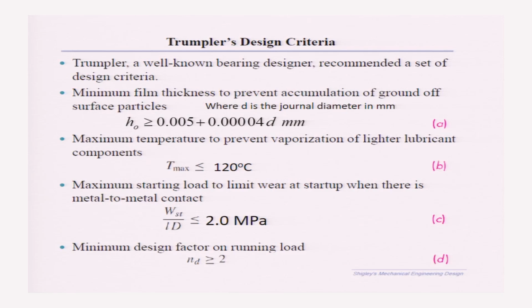In this module on sliding contact bearings, we studied a type of bearing which is very simple. There will be a journal and a bushing or a bearing, and in between that will be the lubricant, and due to rotation of the shaft, pressure is self generated, and that is called the hydrodynamic pressure.